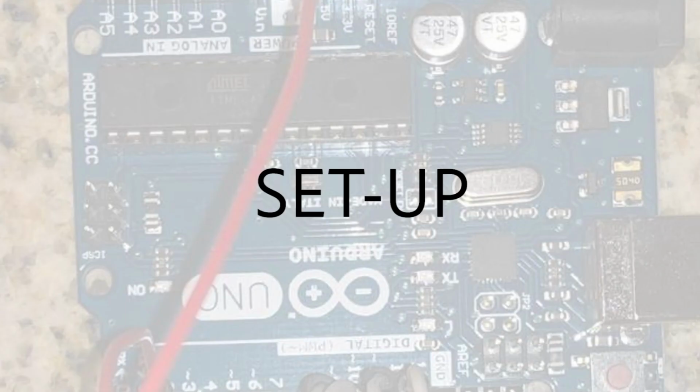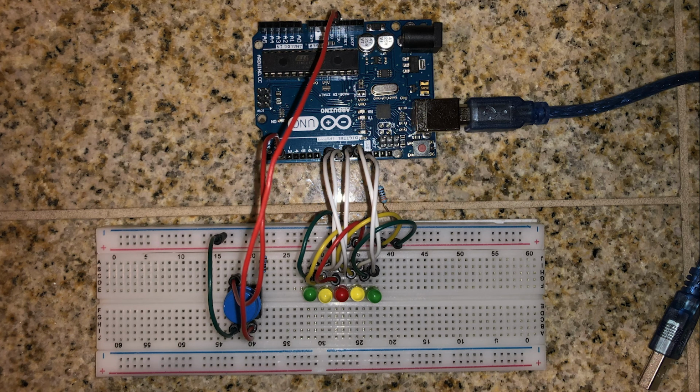For the setup, one jumper cable will be connected to the 5-volt pin and the other end to one of the ends of the button. The second jumper cable will be connected to pin number 2 and one end of the button. And then the 10,000 ohm resistor will be connected to the negative column and to the button.